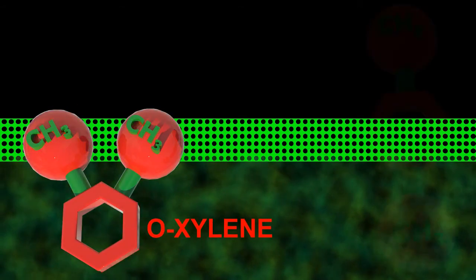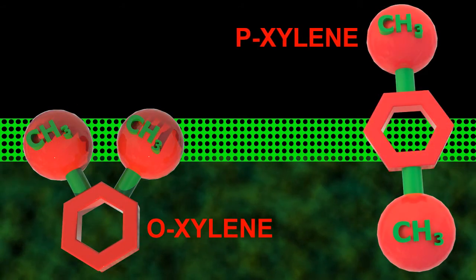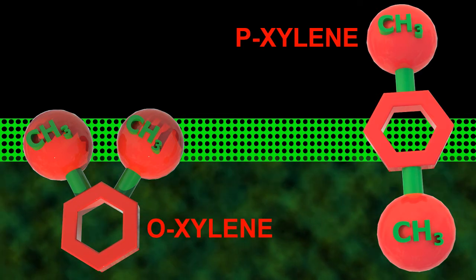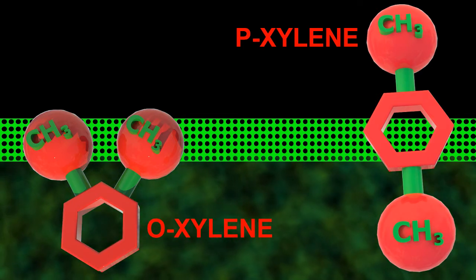For example, a crystalline regular structure will permit the passage of gas more readily. Likewise, the configuration of the VOC vapour molecule will dictate how easily they can pass, some molecules being significantly more streamlined than others. As we can see, having these complex relationships easily summarised is an important factor in ensuring the design is appropriately tailored to the application.